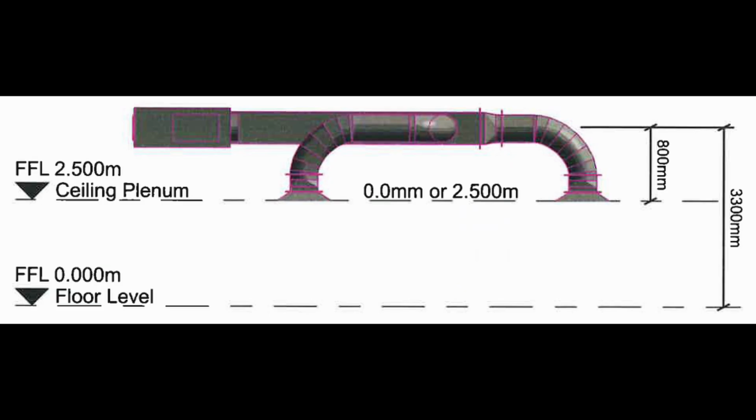Levels and placement strategy. System families like walls and stairs have both a base and top level. Custom families generally have a single base level with a height or offset. When placing M.E.P equipment in ceilings, teams often debate how many levels to create. Some use only FFL levels, others create bundles of levels: FFL, SSL, floor soffit, ceiling plenum.